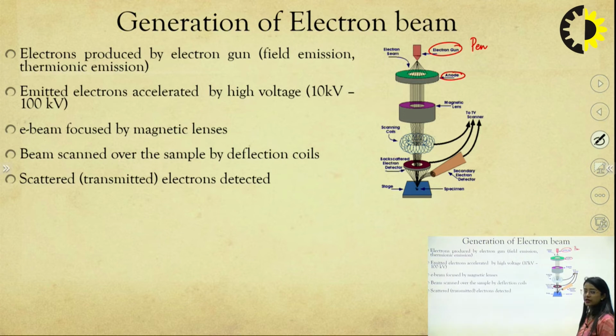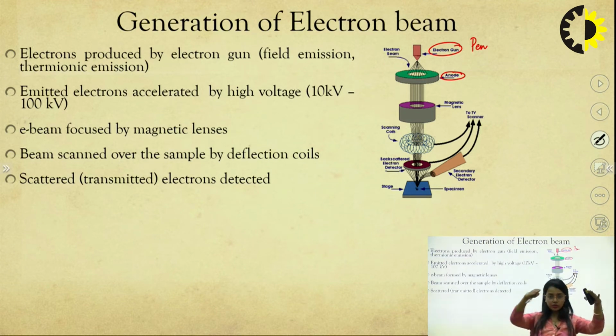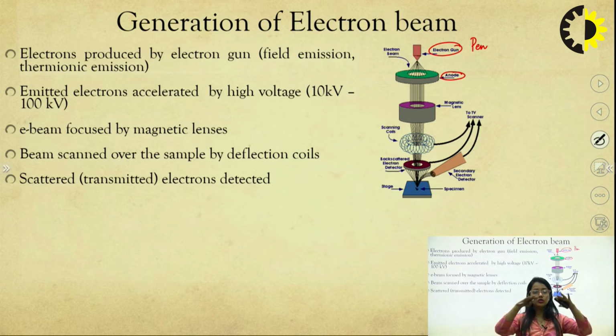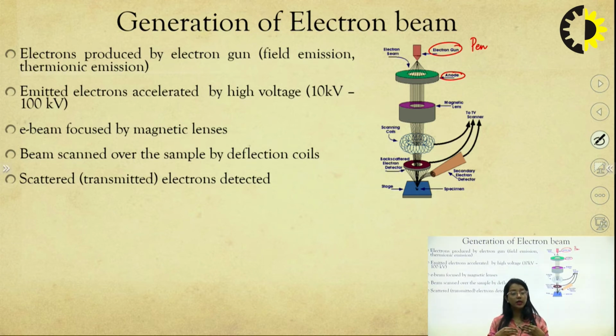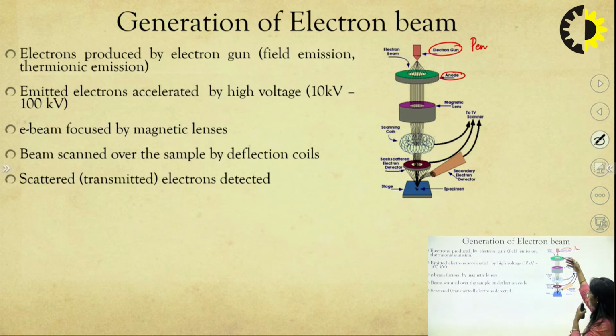So what is this anode actually doing? The scattering of electrons is confined now. So no more scattering is taking place, and then the electrons will fall down in a particular pattern. So how does this help? This helps us to get a better focus on the substrate or on the wafer. So what is actually happening here? This anode is helping. We can see that before this green layer, all the electron beams were scattered like this, and now after this anode, these are very straight and very focused.